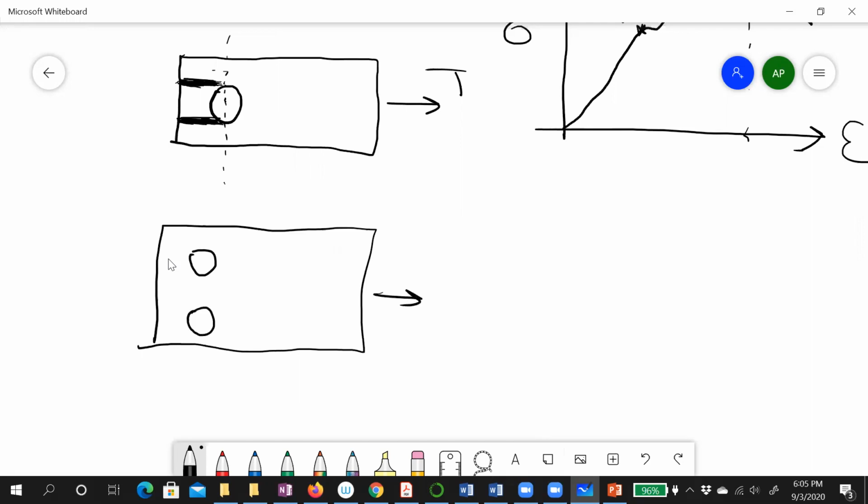So this is 1 plane, this is 2 plane, this is 3 plane, this is 4 plane. 4 planes of shear, but 2 planes of bearing, right? 2 planes of bearing, but 4 planes of shear, right? Does it make sense to you? Yes, I get it now. Yeah, just ask me, because I know it's a confusion, I guess on the same kind of question.